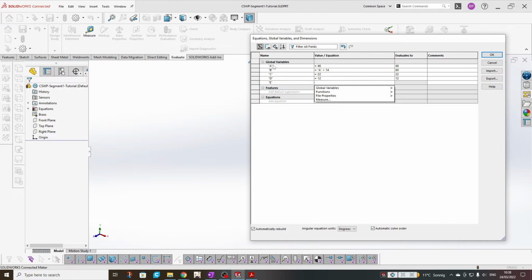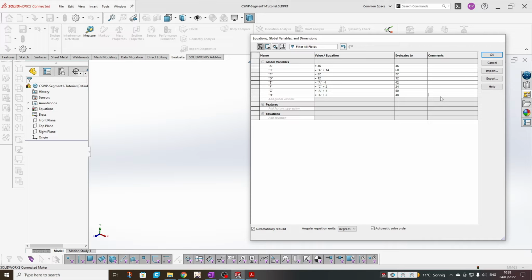Now, if you're wondering why this knowledge is needed: when you're creating a part which will be a family, like for example a bolt or a connector, usually some sizes are changing while other relations stay the same. And if you're working in a company that has a big family of files, it's much easier and better to use global variables for this definition, so you can ease your work.